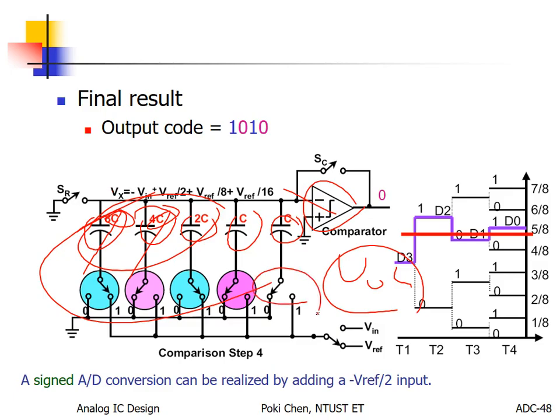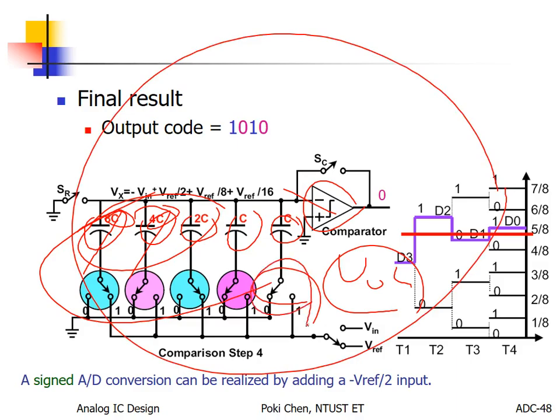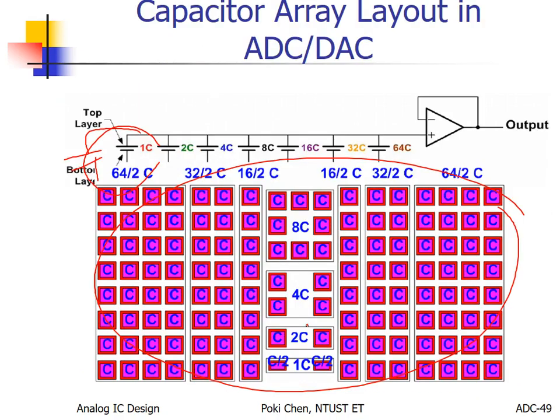You can see? It needs to be switched. In the past, a dummy capacitor doesn't need to be switched, right? But in this circuit, it needs to be switched. Yeah, 2 Cs. And the even more serious mistake is here. For MSB layout, the concept is quite good for you to learn.